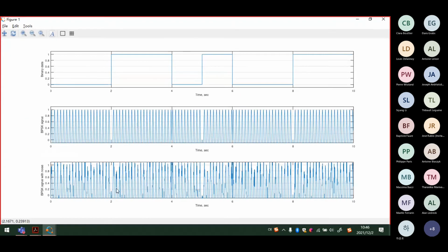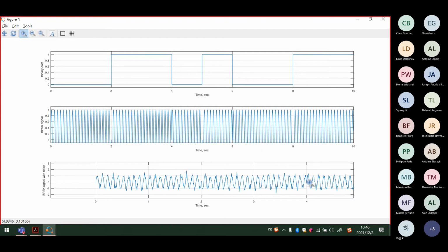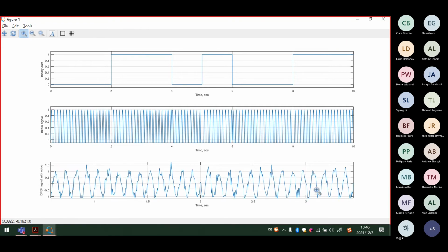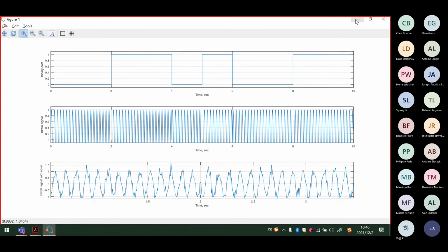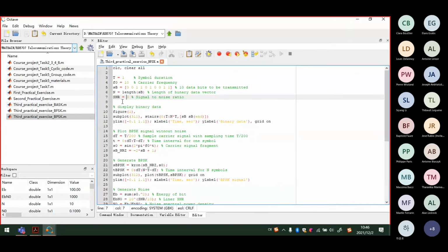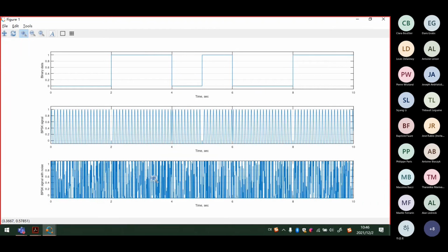And you will see the modulated signal plus the noise. It still has a very obvious difference in its phase. Yeah, here we can also see the phase. So 30 will be quite a good value, and we can still decrease it to like 50. Let's go on. Yes, for the 15, nothing can be recognized.